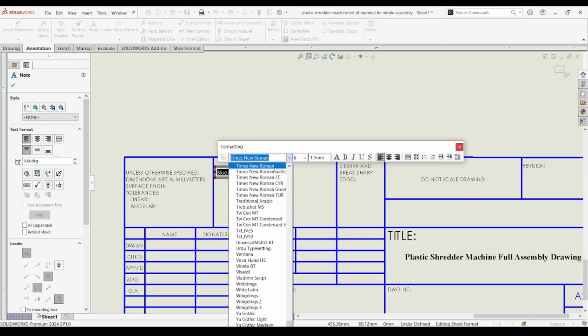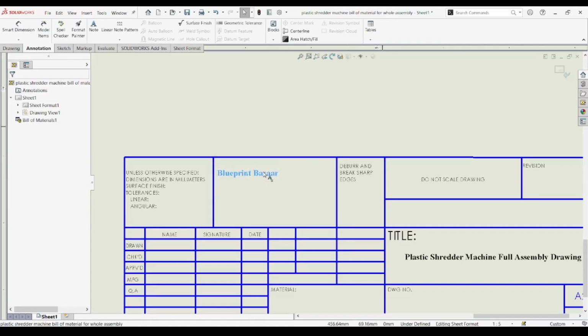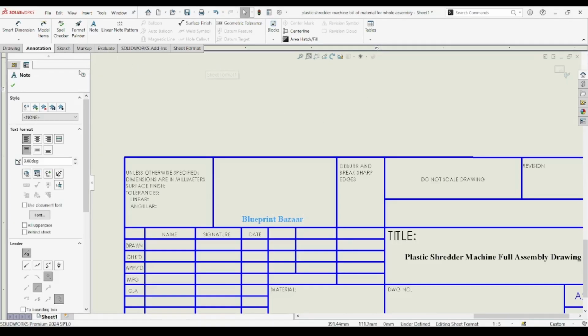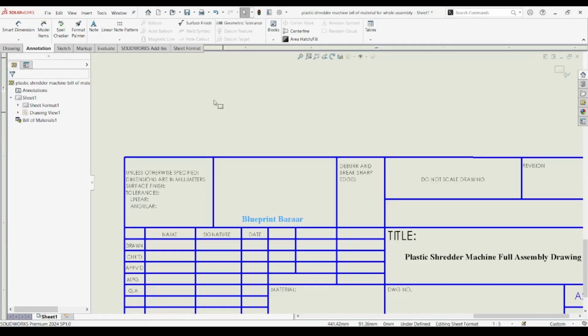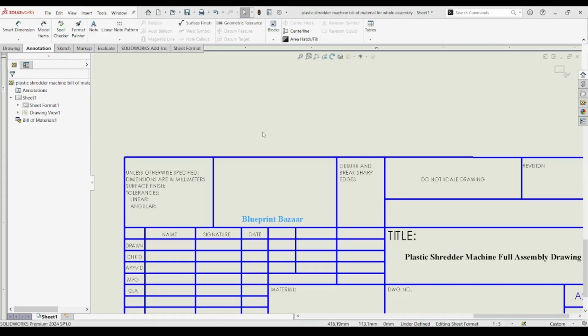We also dive into exploded view drawings, which are particularly useful for assemblies like this plastic shredder. Using the exploded view tool, we generate clear, sequential assembly steps. Combined with auto-ballooned BOMs, these drawings become highly valuable for fabrication and assembly teams, especially when dealing with dozens of repeating components like blades and spacers.